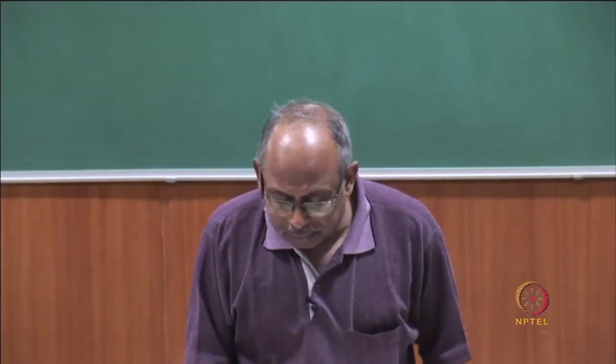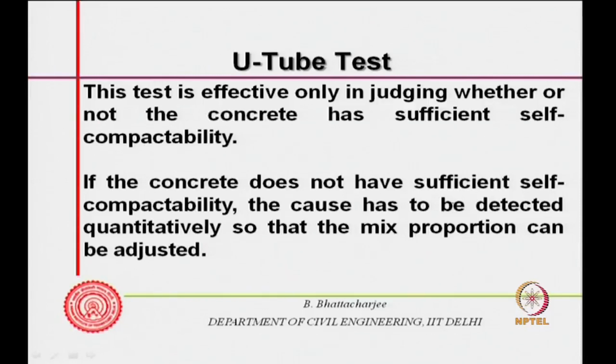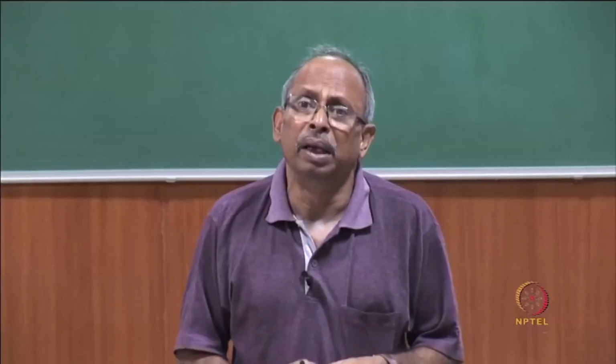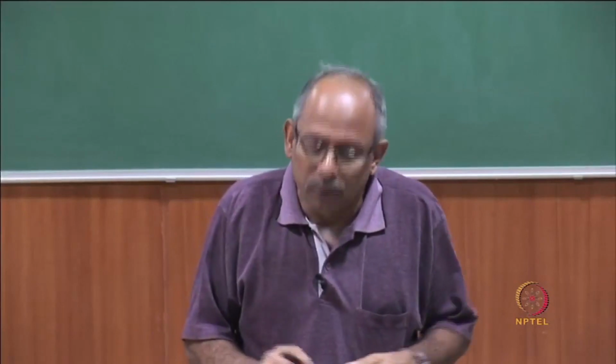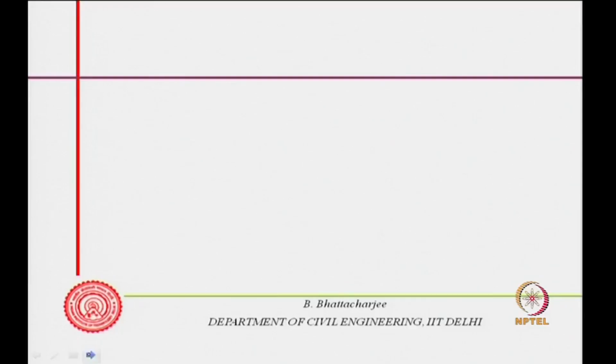If the concrete does not have sufficient self compactability, we have to detect the cause, and the mix proportion has to be adjusted. There should not be any void in the system; it should compact on its own. So, this looks for self compactability.